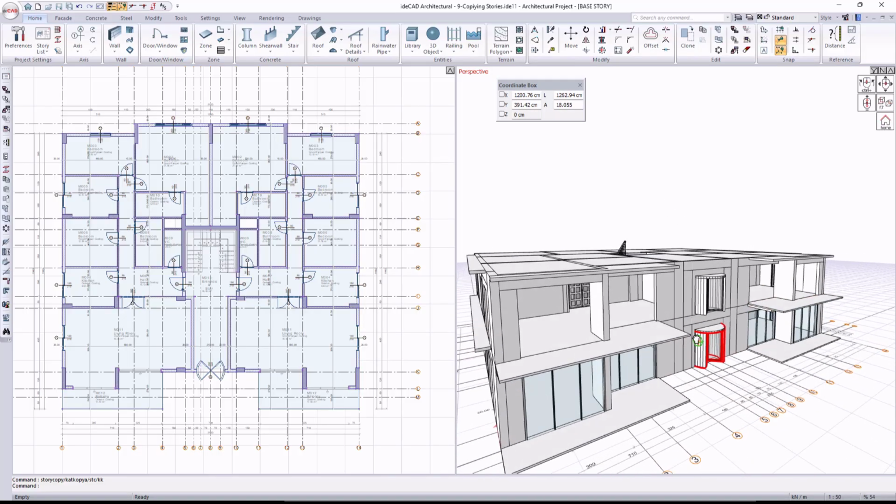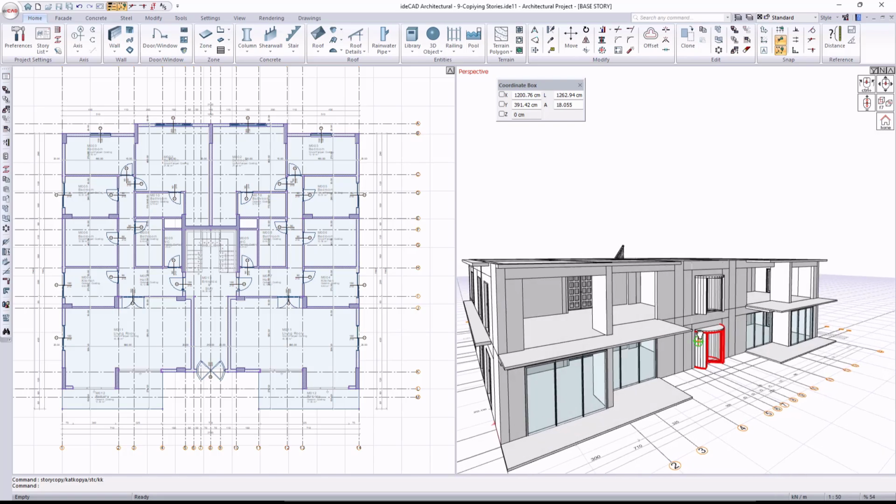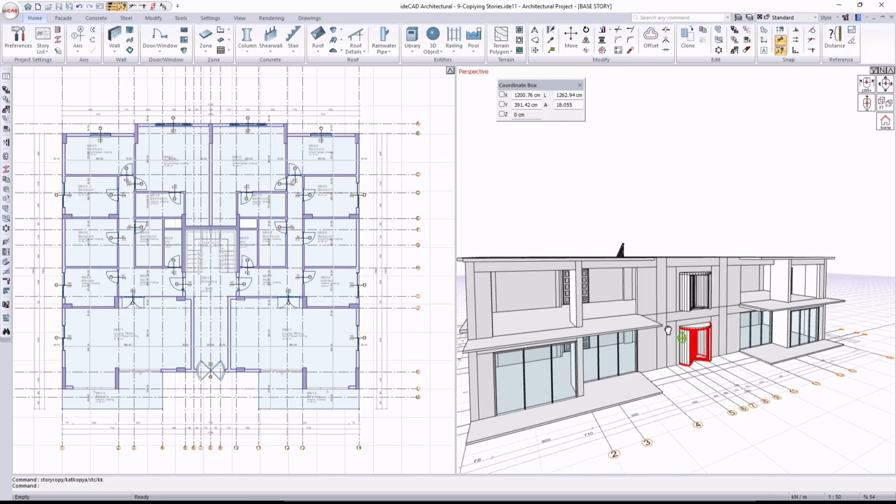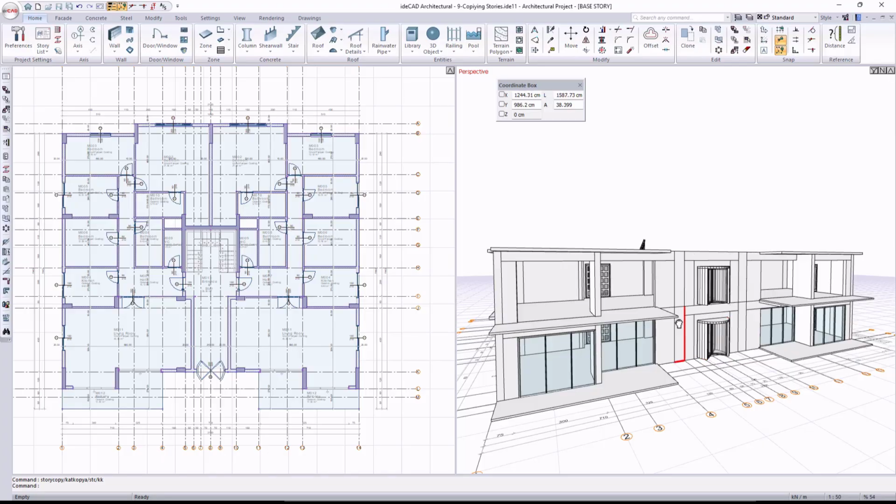After the operation, it may be observed that some facade openings lack elements. This occurs because the Copy Curtain Walls option was not enabled, and therefore curtain walls were not included in the copy. Select the curtain wall objects.